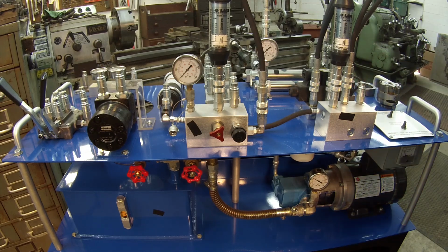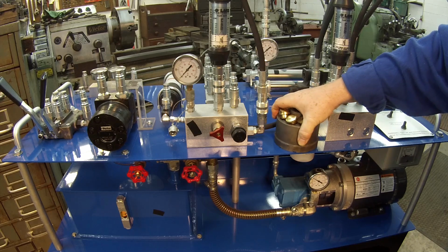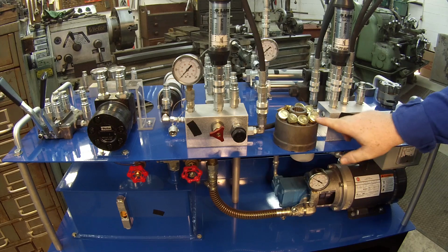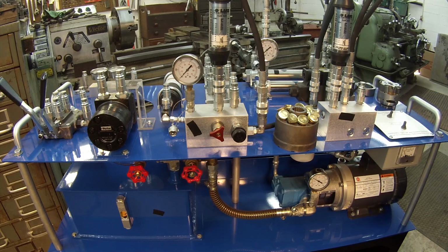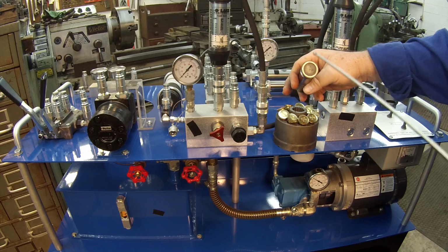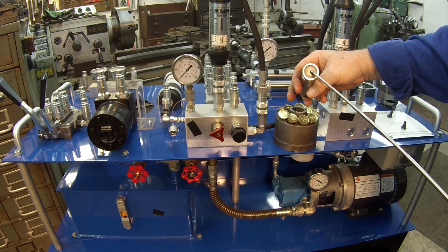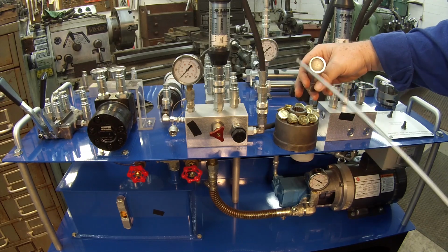Alright, on a piston pump, this is called your rotating group right here on your piston pump, and you see your nice little pretty shoes right there, your little brass shoes that spin around on the inside of your pump. Alright, I don't know if you can see this, I know it's hard to see, but right there in the middle of this piston is how it gets lubricated. Okay? And here's a larger version of that, so hopefully you can see that. That little tiny hole right there in the middle of this piston is how it lubricates itself as it spins around on that what's called a swash plate.